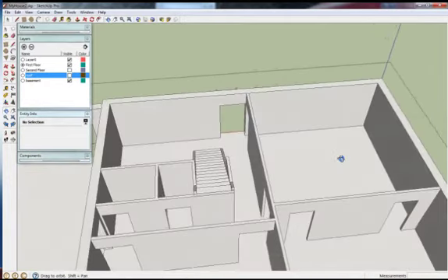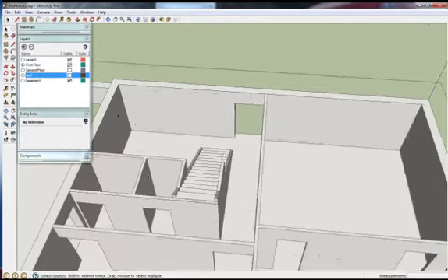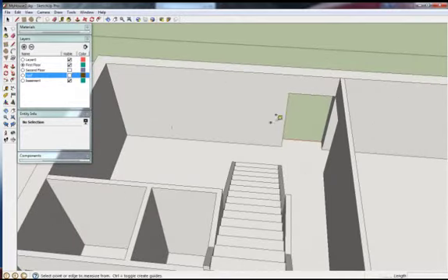Enter the first floor. Measure out where to place the windows. Grab the tape measure. Lay out a reference line at the center of the wall. From that line, lay out a reference line at 3 feet either side of it. Finally, set a reference line 1 foot from the bottom and another 6 feet above it.